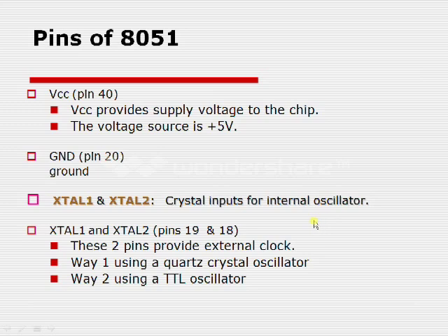An oscillator internally contains one inverting amplifier along with some feedback element, and it has to satisfy the Barkhausen criteria so that we can say that it is an oscillator. Now here we can design that feedback element with the help of RLC components. But there are some drawbacks associated with those components. So that is why we go with one more component, that is the crystal. So we design the feedback element with the help of this crystal. Let us see how to design that.